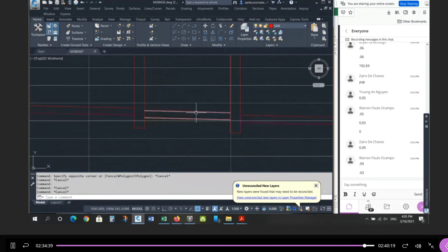And you can actually look at this. Watch. If I delete this pipe, watch the two maintenance holes. I'm not deleting the pipe, I'm deleting the drafted version of it, right? So watch, if I erase this, watch the two maintenance holes. It thinks that pipe's connected at 90 degrees. So if you're not drawing the pipe, it draws the ellipse. If you draw the pipe, then you don't see the ellipse. And that's very powerful.